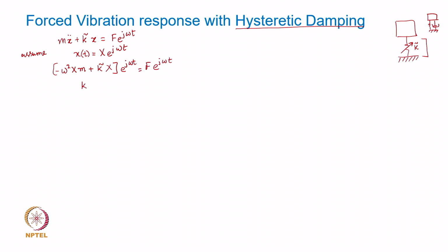Yeah, you remember what is the expression for the complex stiffness? It is K, the stiffness of the material. Okay. So, if I am trying to get that for a simple beam with an end mass here, and this beam is made of steel with certain cross section, then this beam has its own stiffness, the lateral stiffness, right, and the damping property is captured through a parameter called what? Loss factor? Yeah, structural damping coefficient, 1 plus j into beta.